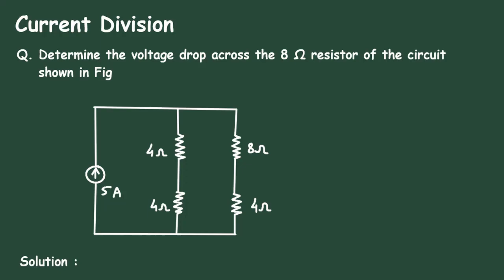So 20 divided by 20 plus this resistance 60. If we solve this, I1 is equal to 40 multiplied by 20 divided by 20 plus 60. So it is 10 ampere. Therefore, the current flowing through the 60 ohm resistor is 10 ampere. So this is how we can find current by using the current division rule.